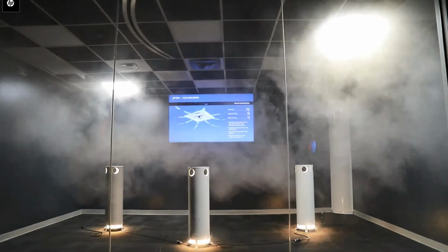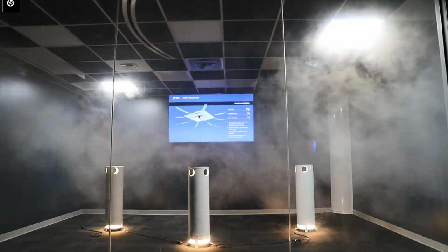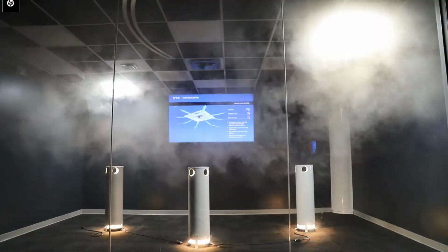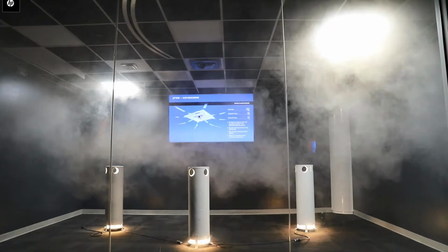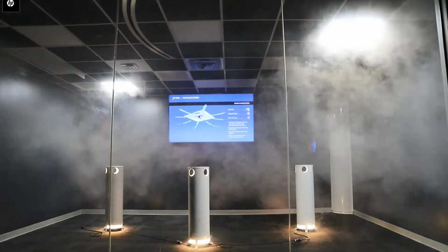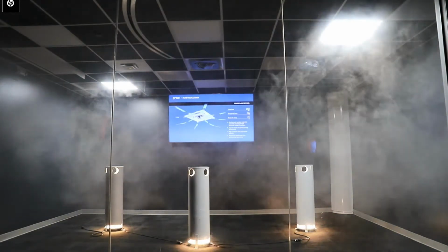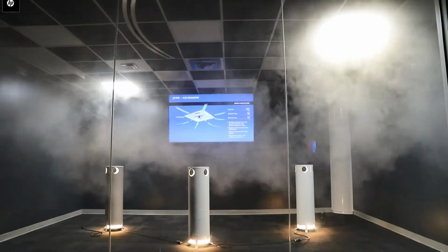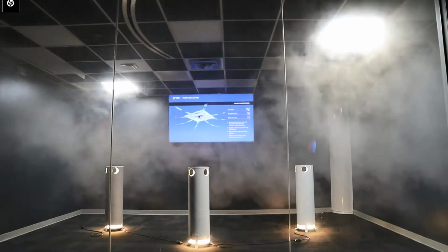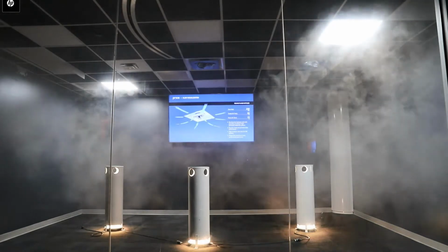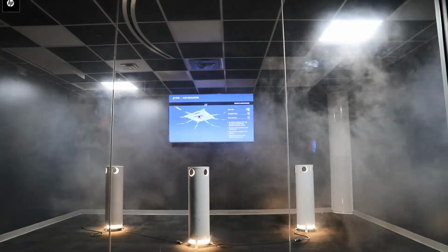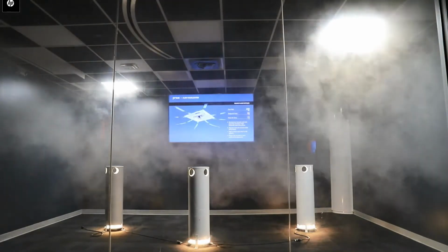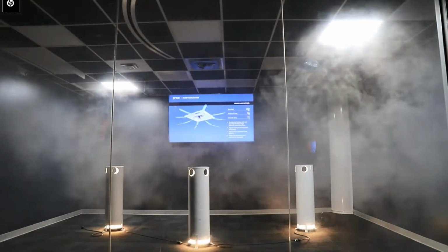The air will then continue to mix throughout the room. We see in this video that there is air moving inside the occupied zone, but it is slow enough that our occupants would not perceive it. There's not a whole lot of discernible pattern at this point, and that's okay. For a mixed air system, we're usually not trying to create a very specific air motion. We're just mixing all the air, and it all becomes turbulent within the space, and there is no discernible pattern.